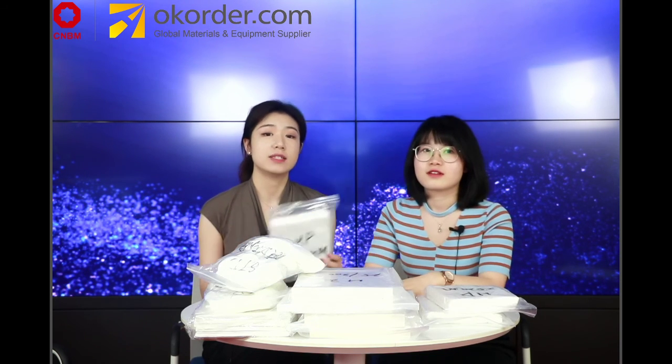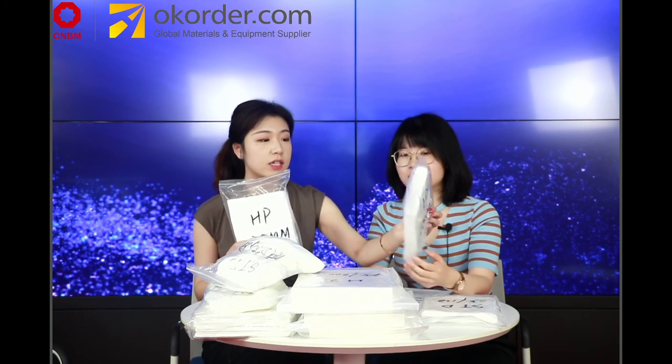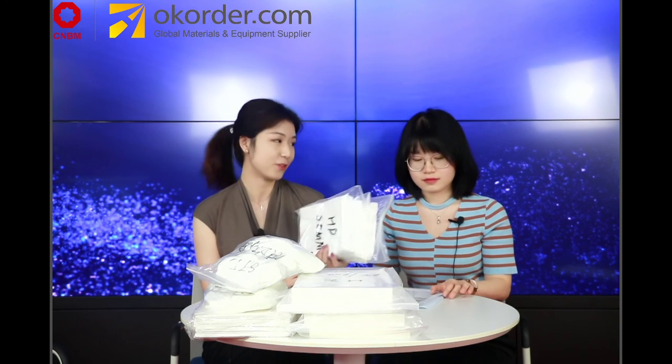And what are the normal standards? So we have three main standards. This one, as you can see here, is HP, and this is also HP. We also have STD, and another one is HC, I believe. The main differences between these three specifications is the temperature. For example, for STD and HP, the temperature is 1,260 Celsius degrees. But for the HC, it's a little bit higher, like 1,430 Celsius degrees.